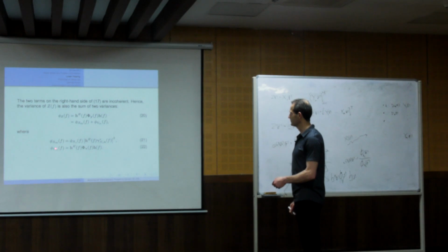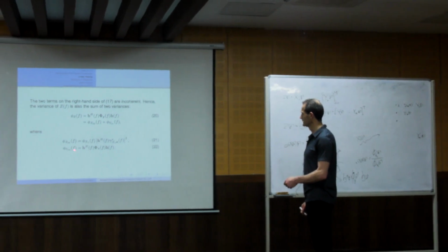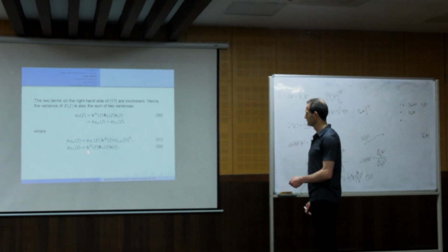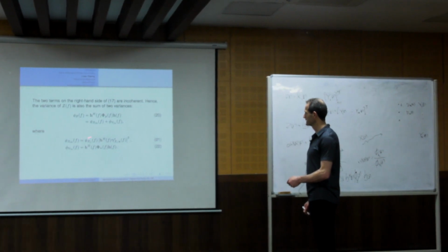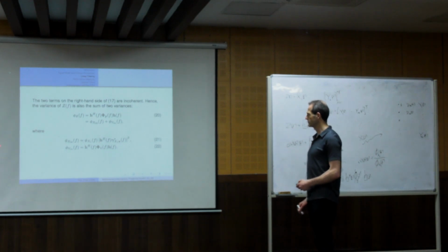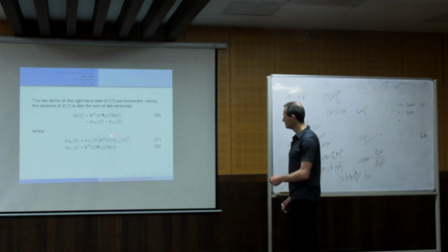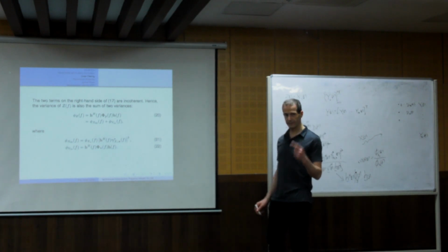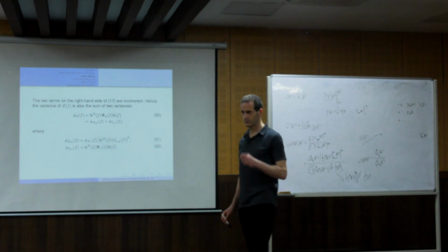This is the variance of the residual noise at the output of the filter. And this is the variance of the filter desired signal at the output of the filter. So this ratio will give us the narrowband output SNR.